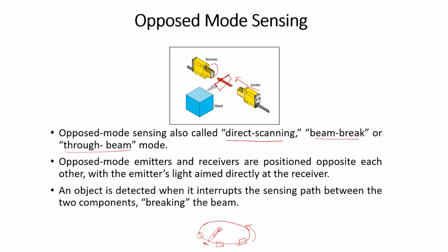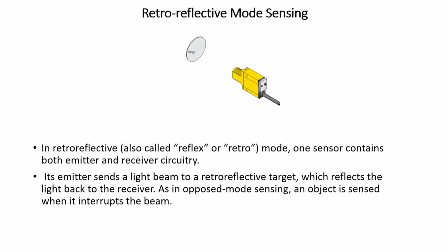So they use this kind of opposed mode sensing. So let us say you have two sensors here, okay. As the luggage comes here, it senses that the luggage is approaching, then it immediately stops this particular belt and it allows this whole thing to move fast. And here also, in the same way, between the two positions, wherever the chute is, just before or just after that, you are going to have a similar kind of opposed mode sensing technique. So this is something which is used very much in terms of the position of a system.